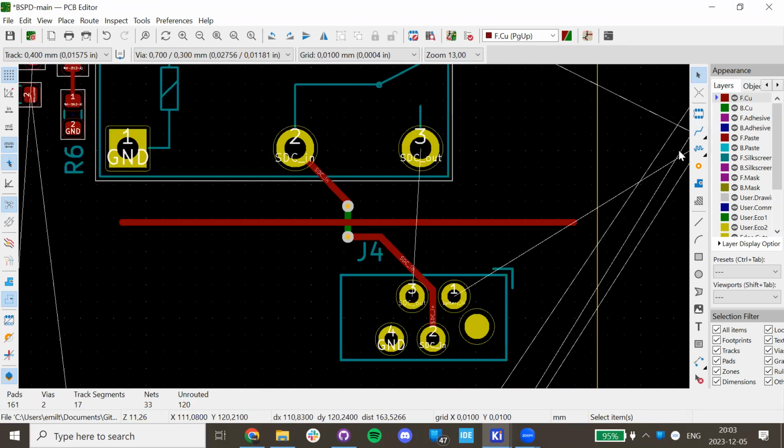And you may have even heard of something called impedance matching. For some designs, the impedance in the traces is so important that the traces even have to be the exact same length. Here you can have tools for routing a differential pair and trying to create different impedances in these traces. If you're doing something like an analog radio transmitter, it is usually very sensitive to these impedances even in the traces.